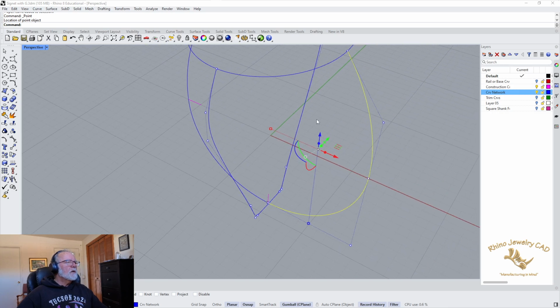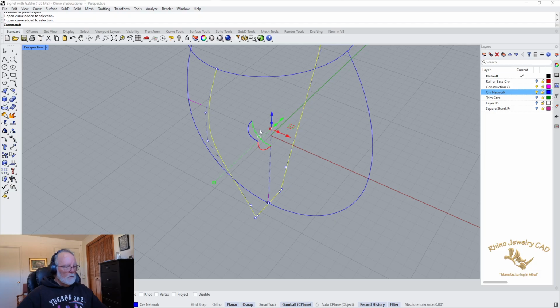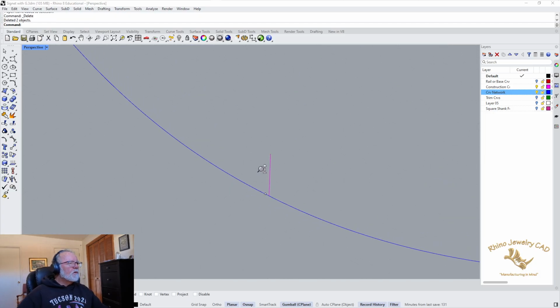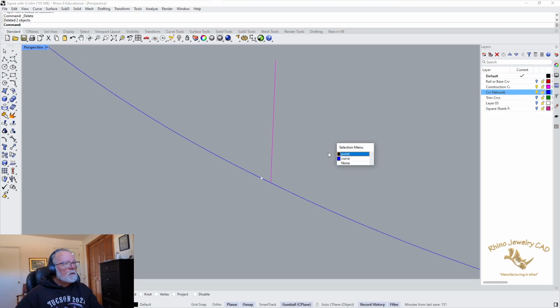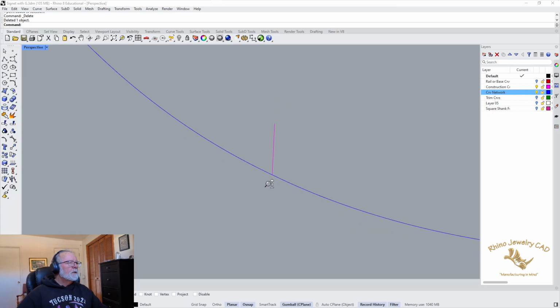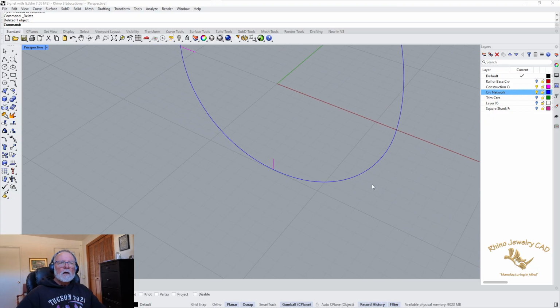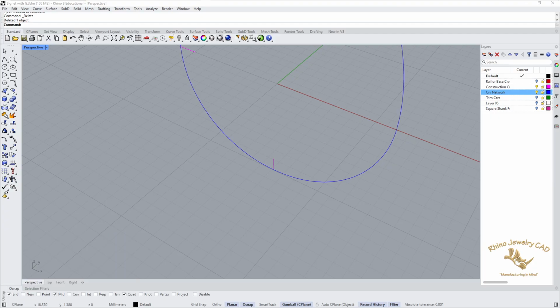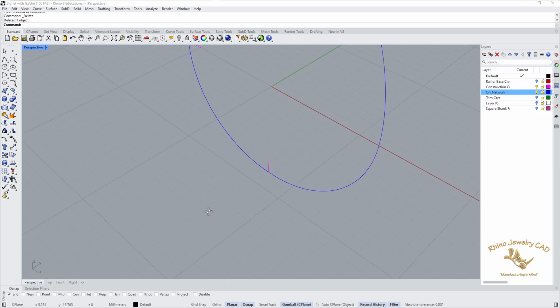let's just delete these two things. And let's re-invoke these. I don't need this either. Point. Let's delete that real quick. And I'm going to turn myself off here so you can see it. There we go. Turn me off so that you can see what's going on down here in the O snaps. Okay, so I just uncheck the quad O snap, leaving the end one on. Mid won't matter. I don't really care if it's there or not, but I turned it off anyway.